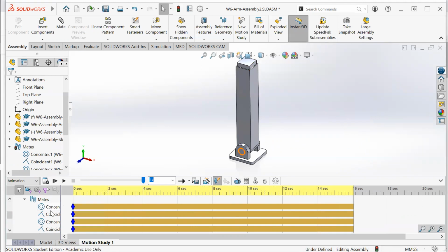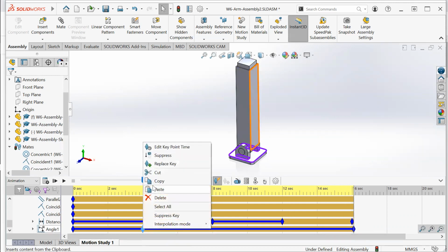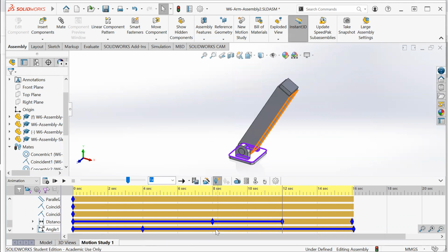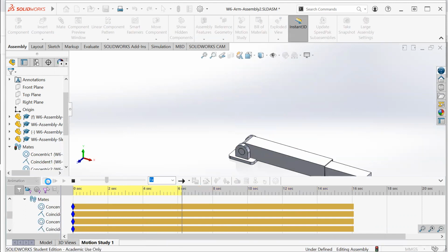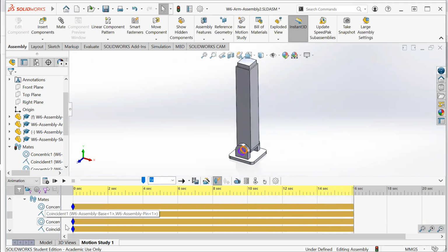Okay, so if you don't want it to go in and out while it's moving, we gotta add a couple more time points here. So here was at fully bent down, and it's starting to go back up in this whole section. So if I want to stay down, I gotta copy this and paste it out here so it stays down while it's pulled out. Okay, so we recalculate. There you go, and then it moves back up and makes a happy sound.